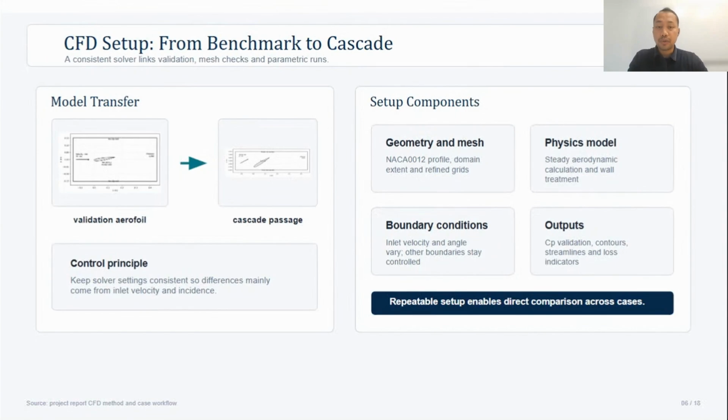And the turbulence model was SST k-omega. The SST k-omega turbulence model is a two-equation model. It combines the near-wall accuracy of the k-omega model and the robustness of the k-epsilon model in the free stream region. By blending both formulations, it provides an improved prediction of boundary layer behavior, flow separation, and pressure gradient, making it suitable for a wide range of flow estimation.